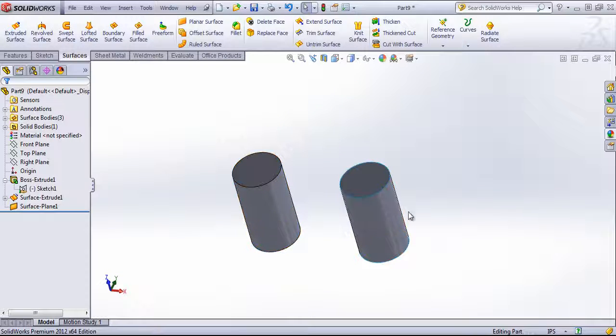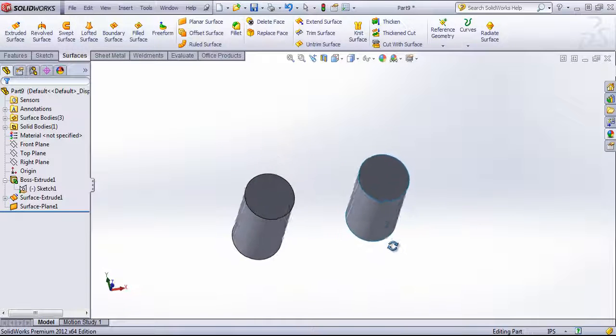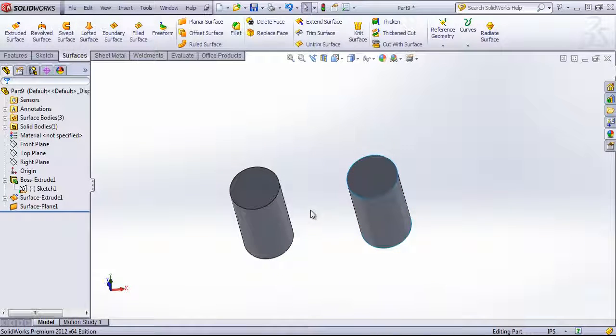So whether you're working with a solid model or a surface model, SOLIDWORKS is pretty much always looking at the external surfaces. Each edge is a boundary between two surfaces. So if you ever get that error that you have a zero thickness geometry, SOLIDWORKS is seeing too many faces connecting at a single edge, so it has issues developing that geometry.